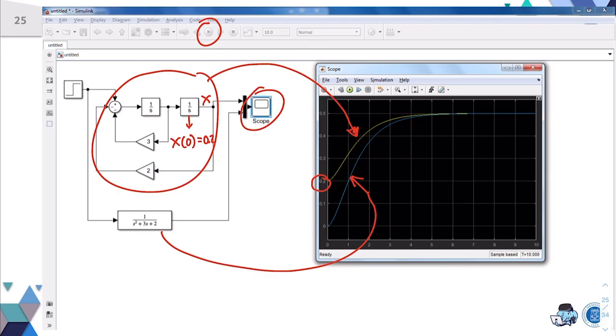So be careful. Please note that the transfer function method can replace the integral method if all initial conditions are 0. You cannot replace the integral method by the transfer function method if the initial conditions are non-zero.